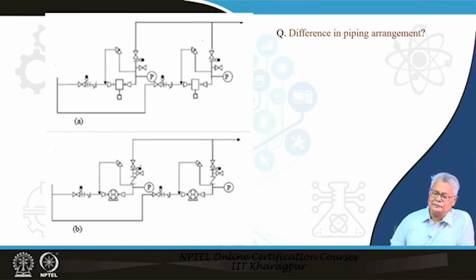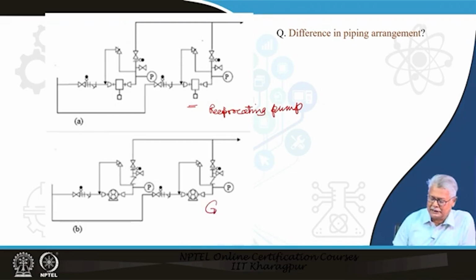That was the case with a centrifugal pump. In case of a centrifugal pump, we could shut the discharge valve and stop the flow without stopping the pump, but I should not do it for a very long time. Why we cannot do this, we can talk about later on. You will find here a reciprocating pump. And what you have here is a gear pump.